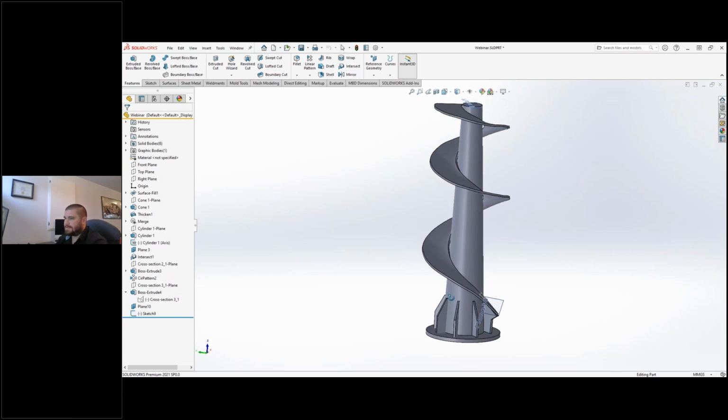In this case, I would have probably just used a scan to overlay it to make sure I get the right pitch or close to the right pitch, because this one probably is made by hand, bent by hand, and then welded, so it moved a lot. So if we want to do an as is reproduction, I wouldn't necessarily use this helix because this is too, let's say, perfect.